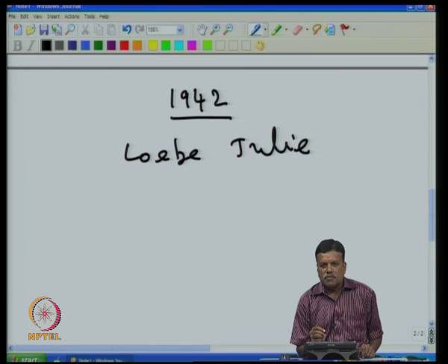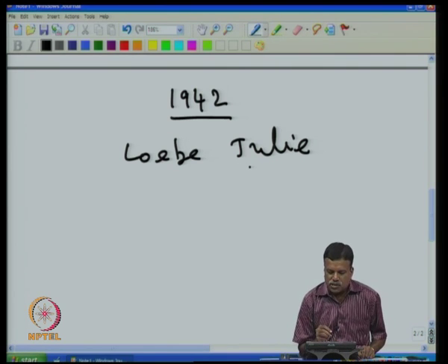And when you amplify a DC voltage, the inherent problem that we have discussed so far, that the output voltage can change due to temperature and due to the supply voltage, will not be there anymore. Also, one need not struggle hard to bias the transistor and then select the resistances and so on. Everything can be inbuilt, and one can use the amplifier as it is. That was the job given to Jolly, and he did that work remarkably.